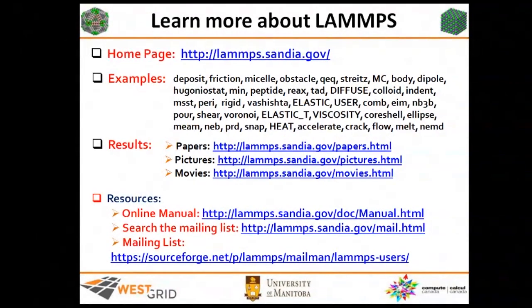To learn more about LAMMPS, you just have to go to the website. There are some examples. Before running your own simulation, you can start by running the examples that are provided. Most of the examples work, but if something doesn't work, it doesn't mean that the problem is in the script; maybe it is in the version of LAMMPS you built.